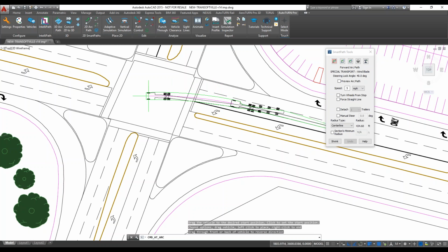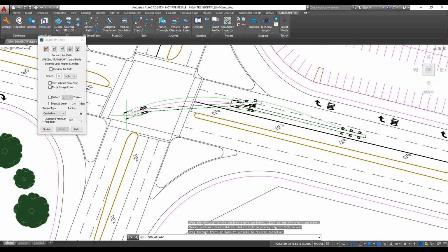And you can see right now my axles are steering, the rear axles are steering, and this is based on the steering linkages that we define for this vehicle. I can bring it up to this point, but you see if I continue, my axles eventually are going to go over my median there. So these vehicles usually have the option for the driver or a second driver to control the steering of the steerable axles. You can see now that I switch, they're going all over the place. They're not steering because the control of the steering is all on me.